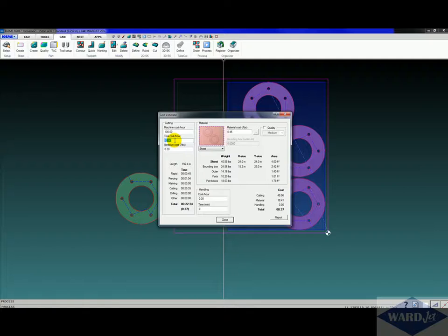So if this is a part we're going to be cutting with a 1440 nozzle combination, or essentially a 50 horsepower pump, we usually estimate about $35 an hour in consumables to run a 1440 nozzle combination, and about $23 of that is going to be abrasive, which means about $12 of that should be other consumable items like your high pressure lines, job shop grates, things like that that are outside of abrasive. Of course, nozzles, orifices, high pressure seals, those sorts of things fall into that number there.